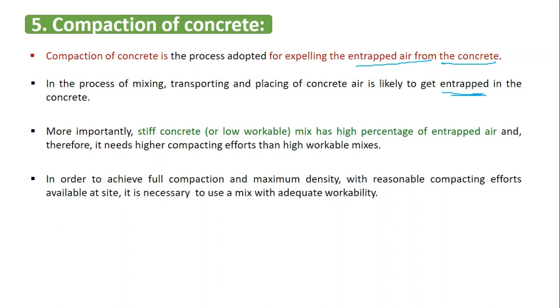Air is not good for the concrete because it leads to porosity and decreases the strength and durability of the concrete. So you have to remove whatever entrapped air is present. That process of removing this entrapped air from the concrete is what we call compaction. We use some equipment in order to compact the concrete.